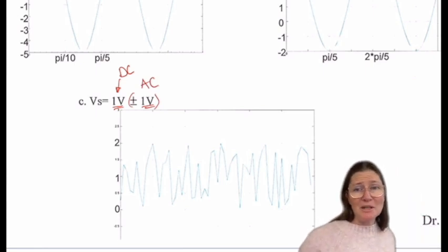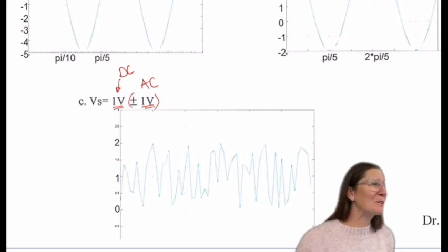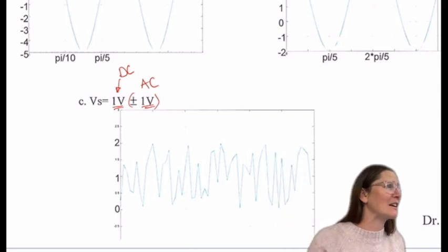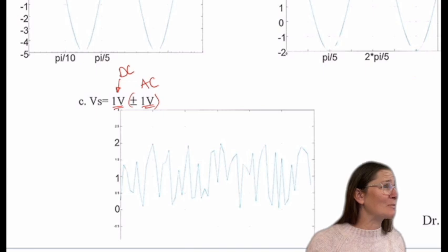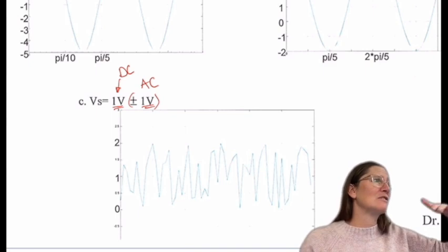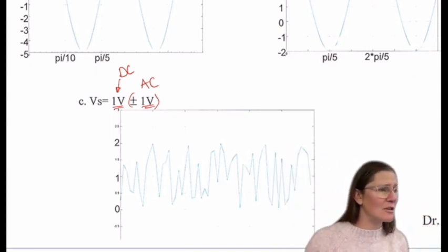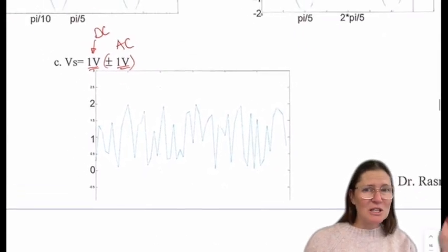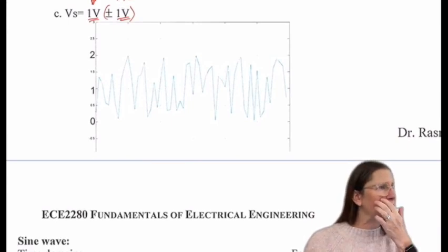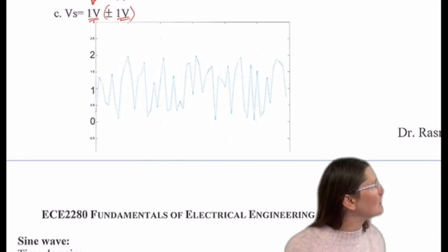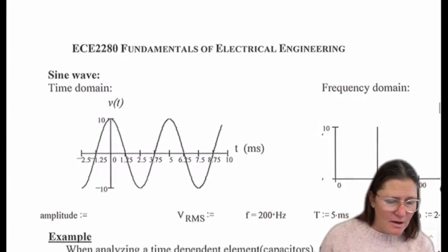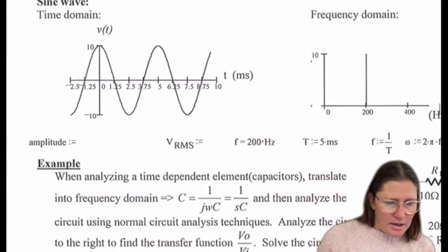This is very common if you guys have looked on your oscilloscope. When you're measuring things that have a little bit of noise, you see a little bit of fluctuation across there. Sometimes it'll be 60 hertz based on the wall signal, so it's picking up some of that through the benches, and you'll see a little 60 hertz signal in there. Other times it can just be some noise itself, introduced by different reasons. So it would look more like this, just random, in between kind of a high and a low.